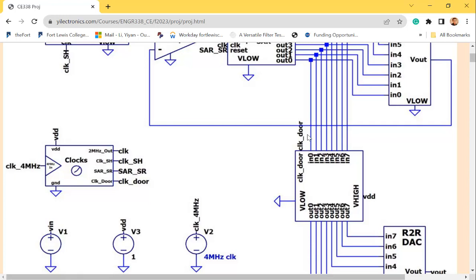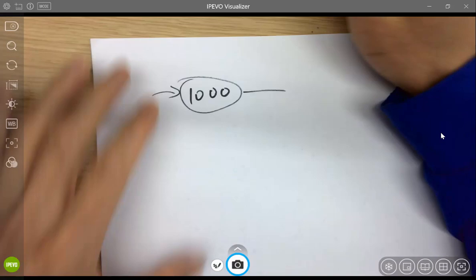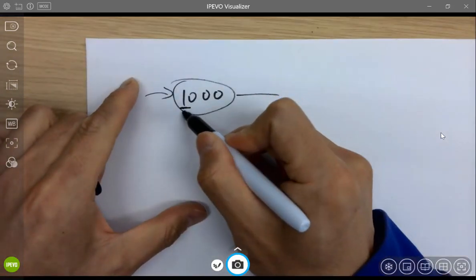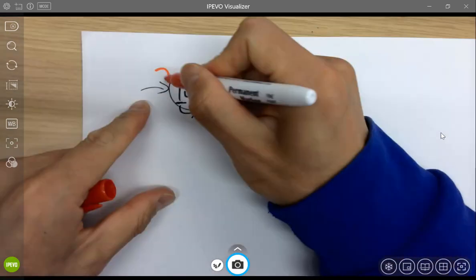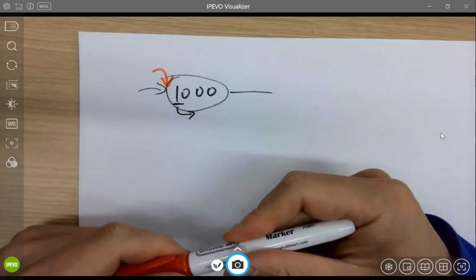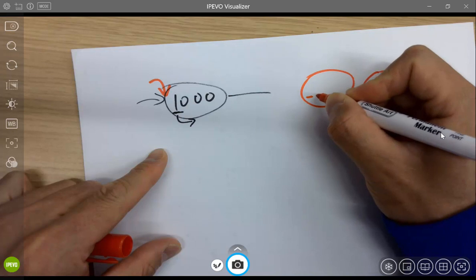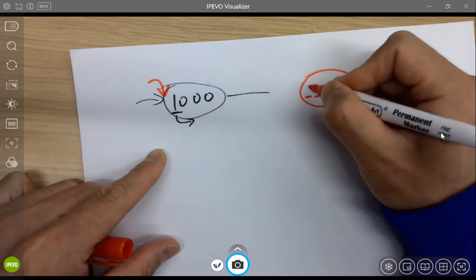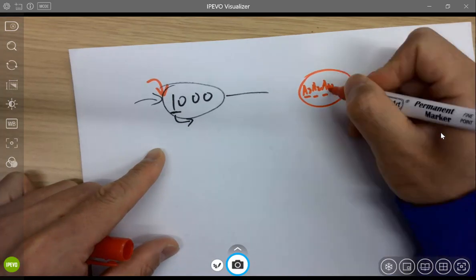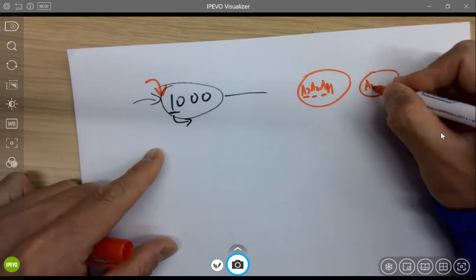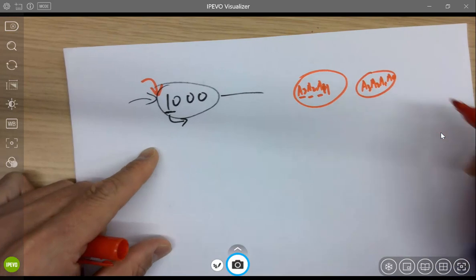So what if you wait until the 9th cycle, right? After the 9th rising edge, the data is already available there. So what if you run another clock? Is it going to change the value here if you run one more cycle? Remember, we come back to the diagram, right? This one is being shifted to the right, and we are adding the comparator's result in the front. Right before the final state, you have whatever, and a 1, which is this one. So this will be A3, A2, A1, and eventually you have A3, A2, A1, A0, right? These are all the comparator's output. That's the final result.